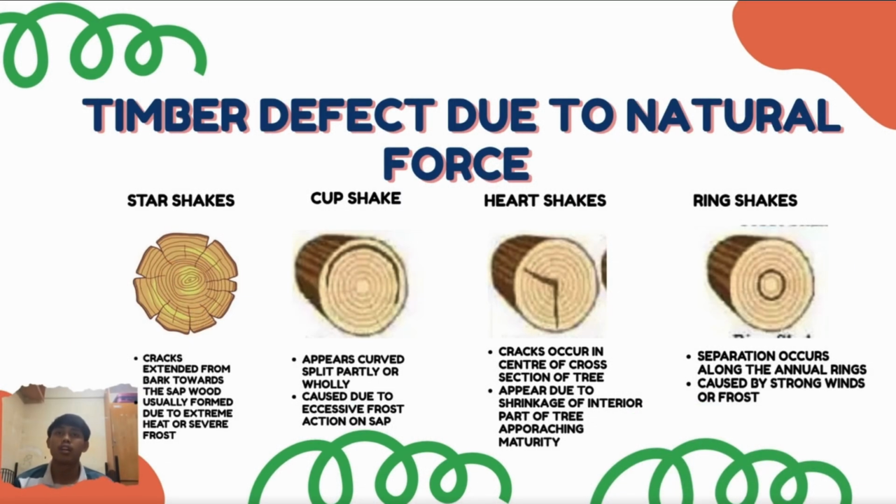In this slide, I show different types of cracks, also known as shakes, in timber. First is the star shape. This crack starts from the outside of the log and extends towards the center. They are usually caused by extreme heat or severe frosts.